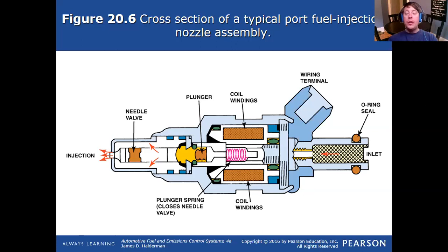So operating injectors at max duty cycle. That's another term that we talk about with fuel injectors: duty cycle. Pulse width on off is in milliseconds. Duty cycle is a percentage of on time versus off time. So all fuel injectors have a maximum duty cycle, roughly 85-90% on time. Meaning that out of a given set of time, if you set 100 seconds, they can only be on for 85 of those seconds. They have to shut.